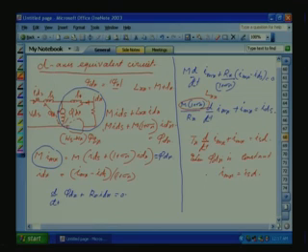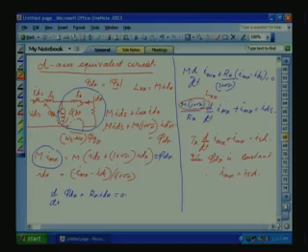Okay. Now, we got the two equations. See, we are injecting current IS into the machine. And the IS we have split into two orthogonal components, ISD and IQS, and ISD is placed along the phi r rotor flux axis. If that is correct, the perpendicular component is proportional to slip, and that will be proportional to torque, and the parallel component along the psi r is the one which is responsible for the flux.